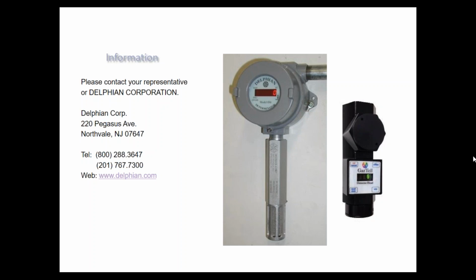Going to your second question real quickly, open path is a whole different animal. I am not a big believer in open path for a whole bunch of reasons. Number one, if your open path goes down, you have zero gas detection. You might have an open path that does the job of 20 single point gas detectors. In 20 detectors, if one goes down, you have 19 left. In an open path, one goes down, you have zero detection.